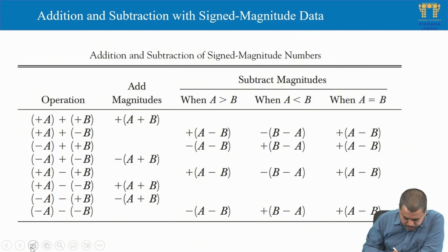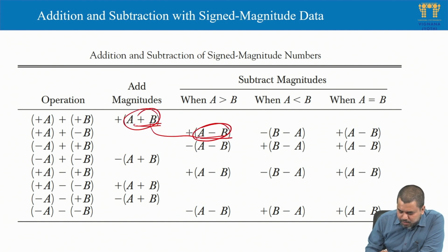To ensure less hardware, we think in a different way. We know that subtraction and addition both can be done with the help of the 2's complement method. So instead of one adder and two subtractors, we can use only one adder and one complementer.